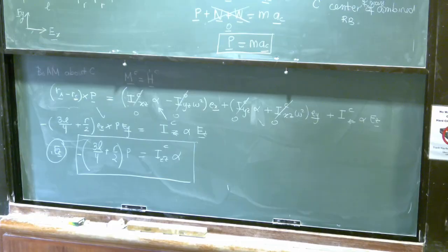For wheel A, investigate the case where the mass of the rim and spokes is negligible and the mass of the bar is concentrated along its center line. For wheel B, assume that the thickness of the rim is negligible compared with its radius so that all the mass is concentrated in the rim. Also specify the minimum coefficient of static friction US required to prevent each wheel from slipping.